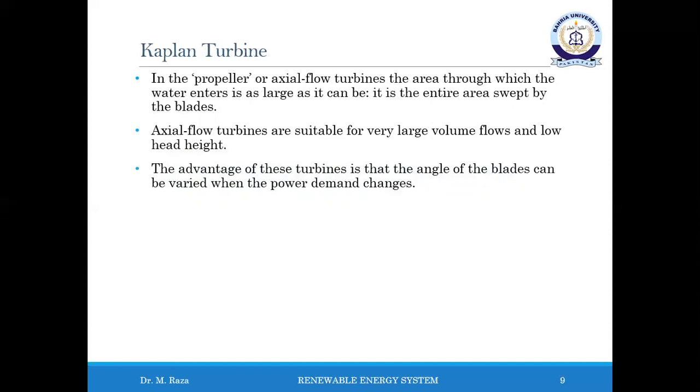Another variant of reaction turbine is the bulb turbine. The bulb turbines are named after the shape of the upstream watertight casting in which the generator is enclosed. Typically, bulb turbines are implemented in low-head hydropower schemes with high output. They are used in hydropower plants with head up to 30 meters and offer reduced size and cost compared to vertical Kaplan turbine due to the almost horizontal water passage in the draft tube, which requires a smaller evacuation.